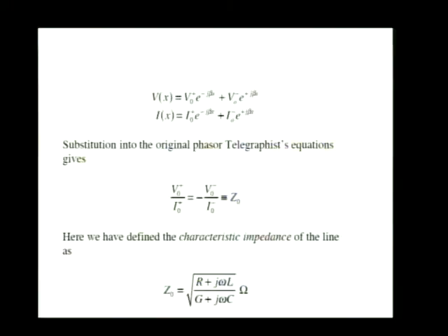50 ohm lines, that's the main type of transmission line that's used in practice. Sometimes you see 75 ohm lines. Very seldom you'll see 150 ohm lines. 50 ohms is almost the universal value for the characteristic impedance of transmission lines. It's a standard.